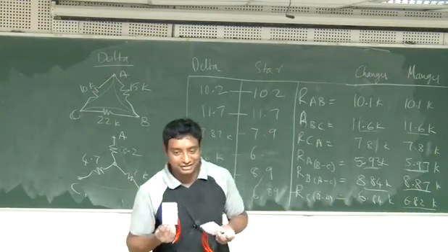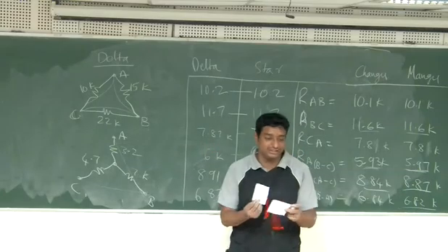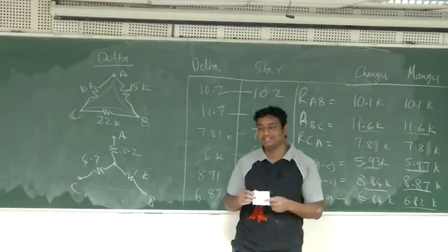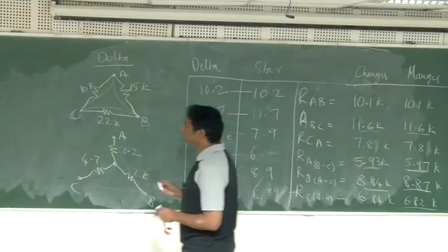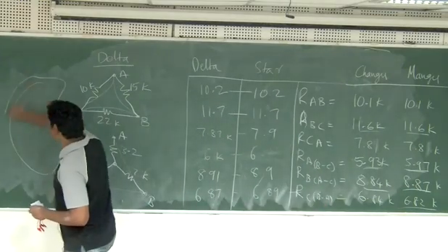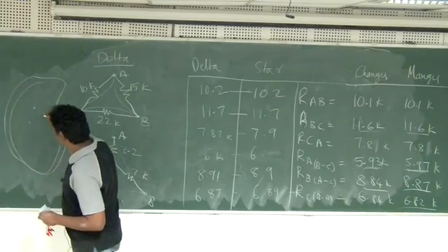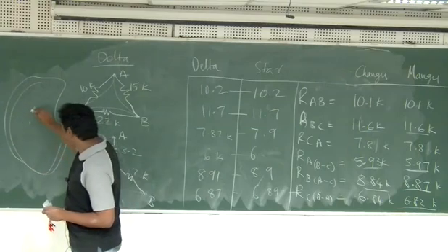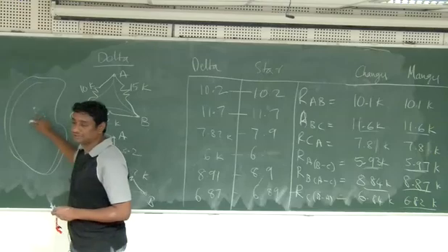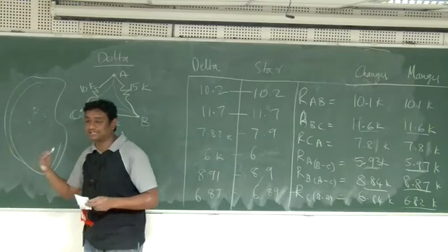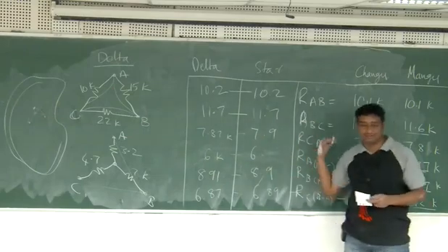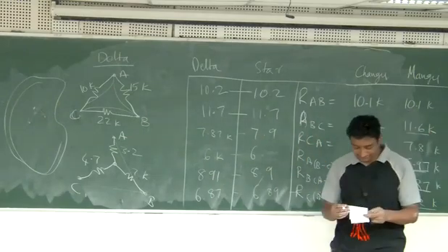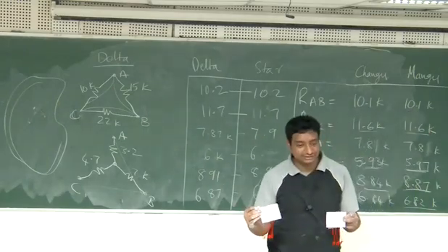That's the whole point. In the star delta transformation, we can't tell the difference. The rest of the circuit cannot tell the difference. You have a large circuit, let's say a very big circuit. In that big circuit, you take 3 points, and if it is delta, you can convert to star. If it is star, you can convert to delta. The rest of the circuit cannot tell the difference, because it behaves exactly the same way, whatever you do. Still, shall we take a guess?